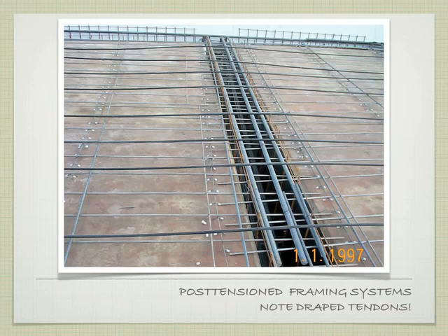We've got reinforcing in the girder, but across the top here, there's our tendon. And generally when you look at something like this, there's less reinforcing because you have this tendon in there. So it drapes. It's at the top of the slab here. It droops down into the bottom of the slab at the midspan.